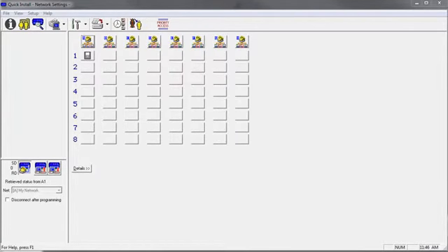To go online with the panel, select the On/Offline icon, pictured as a yellow telephone in the lower left-hand corner. Once the software establishes communication with the node, we will see our panel flash in the appropriate network. In this case, it will be Network A, node number 1. Left-click on the flashing node and select Install Panel.